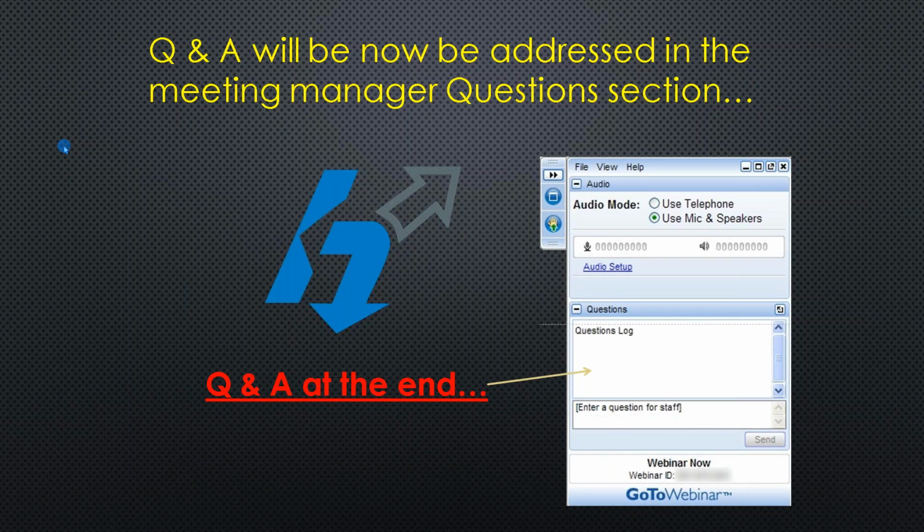And there was another question in that same ballpark. When you're doing the conversions, you were talking about the outlier. Is there a way to isolate that mesh node and suppress the outlier? No, there's no way to isolate a particular node. For that matter, there's no good utility to find which node that is, because your von Mises is simply an average of your first and third principals. To go through there and probe each individual node, we've got better things to do.